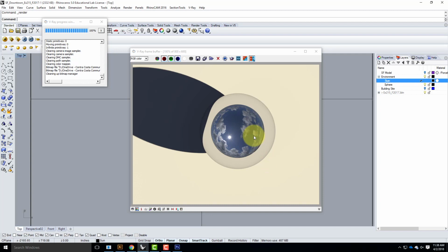Does that make sense? So I'd see with the shadow being right here, I would need the image to rotate so that the sun was there, or I need to rotate my sun to a different time of day so that it would match up over here. So I have 2 different ways of doing it. I can change the image, the HDRI background, or I can change the sun or the time of day. Either way works, and I'll show you both.